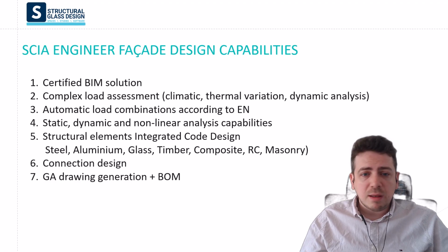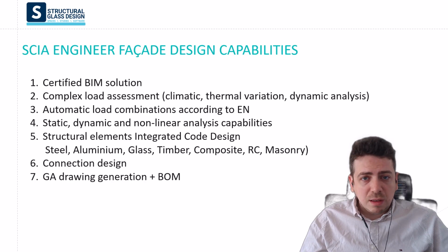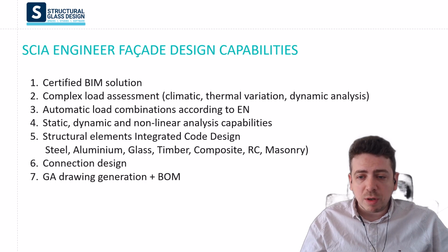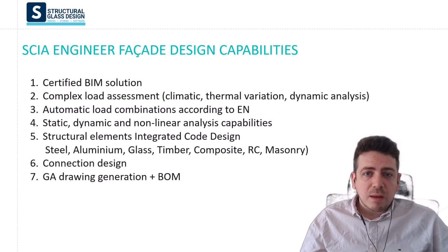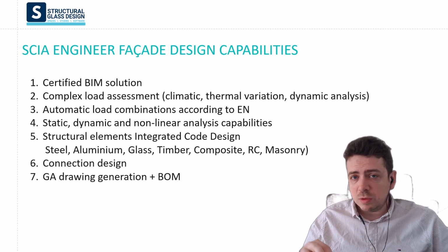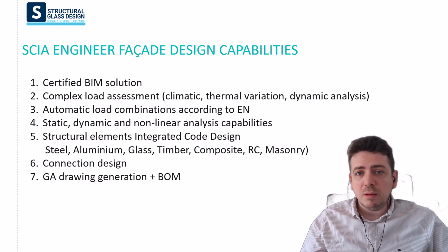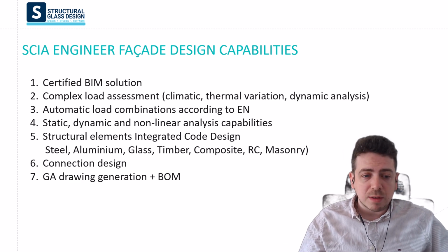It allows static, dynamic, nonlinear analysis, and it also has integrated the design of materials which create these facades, such as aluminium, timber, composite, steel, masonry, and of course this glass part, which we will go into more in depth. And it also allows you to design the connections, which are a key aspect when working with glass elements.